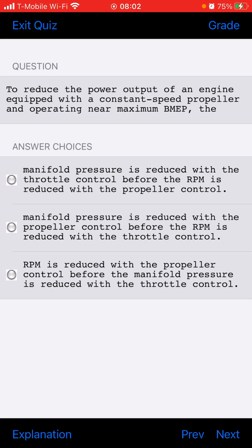So what is the purpose of the power check in a reciprocating engine? To determine satisfactory performance. The power check of the recip engine is done to determine that the engine is developing the correct static RPM.